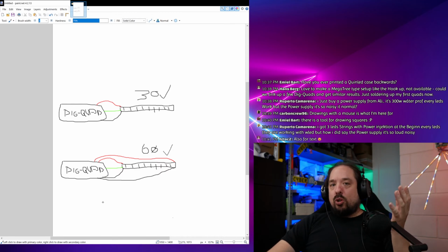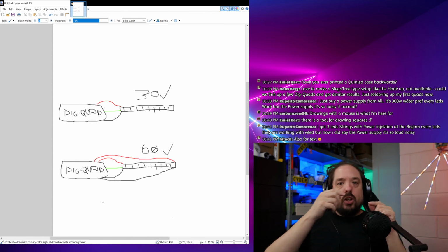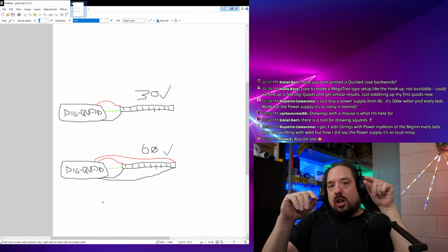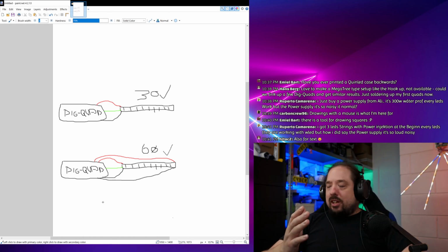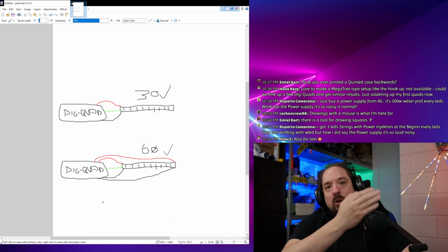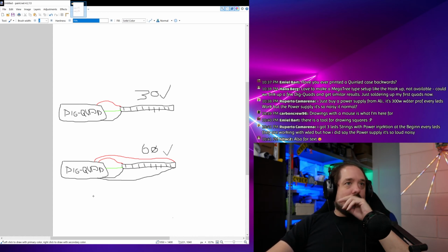You can use a Dig Uno for this because you can just jam 2 cables into the output terminal or use a thicker cable on the output terminal and then use Wago clamps like I've shown in some videos. But that is part of the reason why I introduced the Dig Quad. It has lots of output terminals, so you can do this easier.